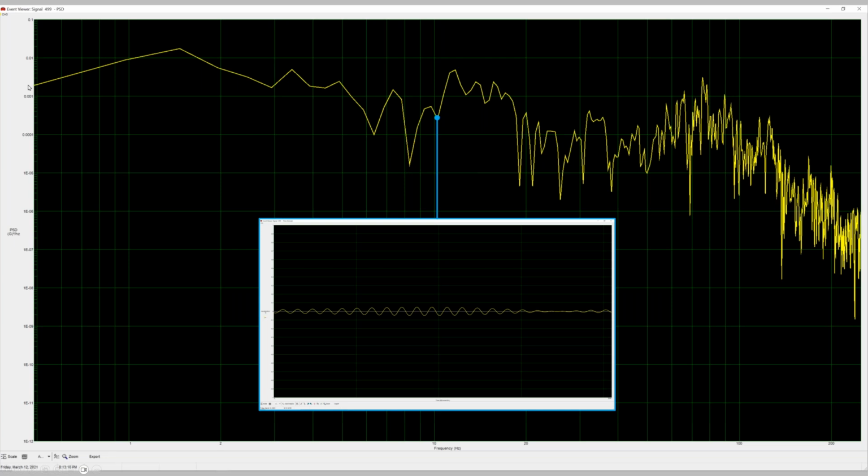Everywhere you see a peak on one of these PSDs from the field basically means there is math being done at that point. So there's one being done here, here, here, here. So it's hundreds of different points where you have the ability to dissect the time domain signal, create basically average time histories or time intensities, and plot those on your PSD plot. And this is one PSD that was created from 2 seconds of real world data. And that's all it is. I can create a PSD on just 2 seconds.